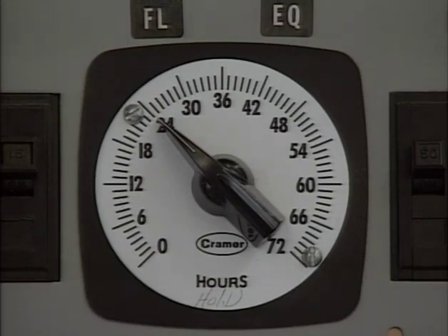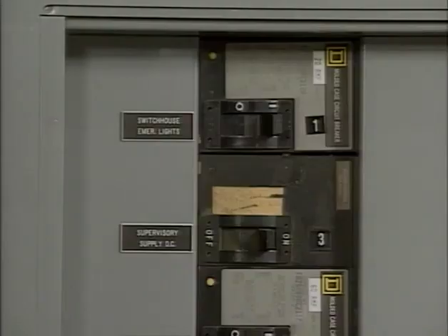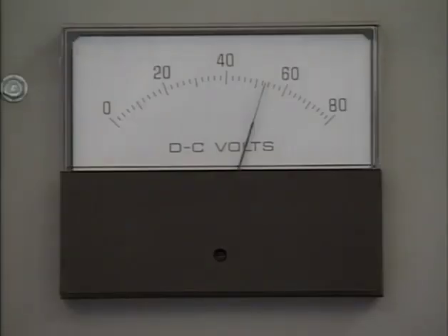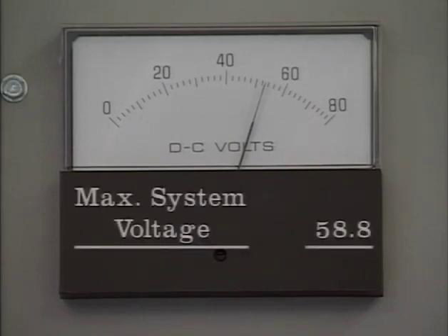The charge is applied at a voltage and for a period of time that's specified either by the cell manufacturer or by company requirements. In general, the freshening charge is determined by the maximum voltage that the DC system loads can tolerate, or the maximum charger voltage if load is not yet connected. For example, the maximum allowable voltage for this system is 58.8 volts. Voltage any higher than this may damage the control and protection circuits.